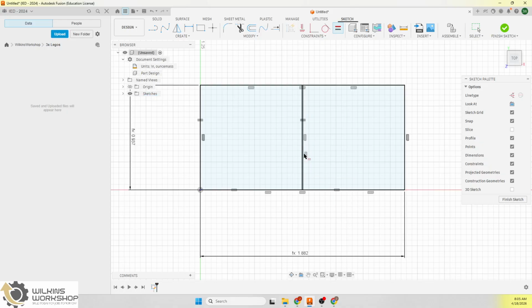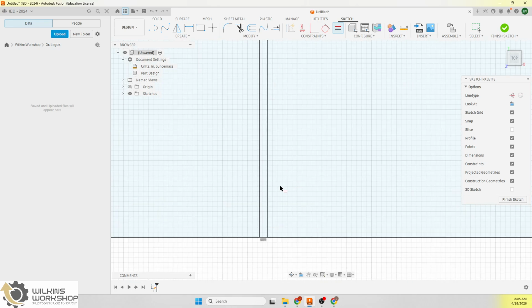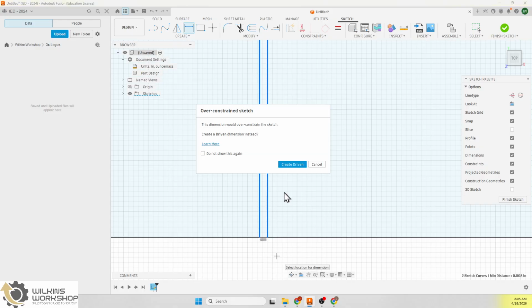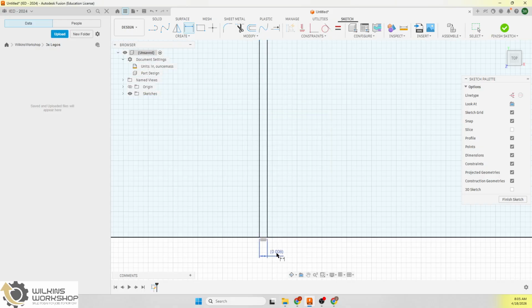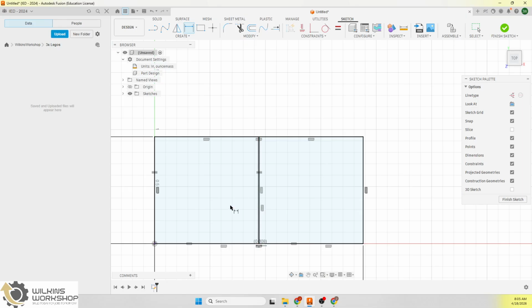But there you go. Well, see, those are two 1x1s, and notice that they don't touch. There is this air gap between them that should be roughly 8 thousandths, which is essentially 2 sheets of paper. So if I were to dimension those 2 spots, you'll see that you've got an 8 thousandth gap when you put 2 Lego pieces that are 1x1s on top of a 1x2.